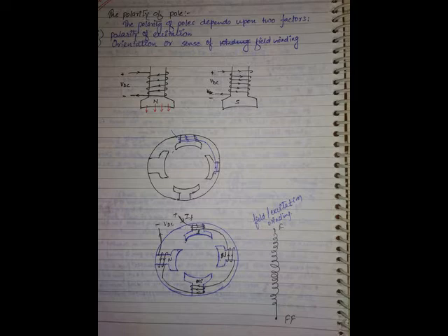The difference between that and this is, if you see eddy currents, here also eddy currents flow, but where? They will flow only in each lamination, because between each lamination thin insulation is there. So by electrically isolating, the flux will link, flux will pass through the core, no problem.